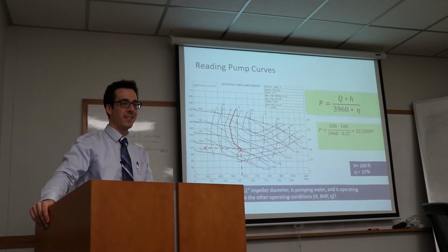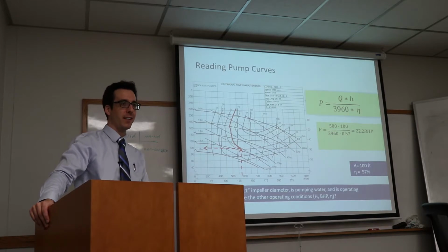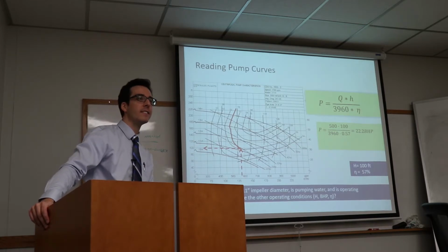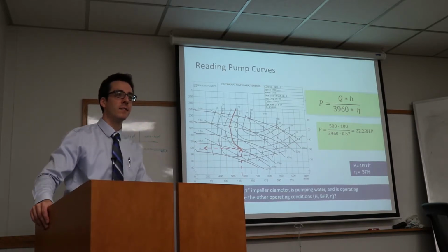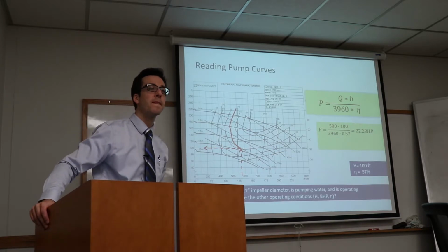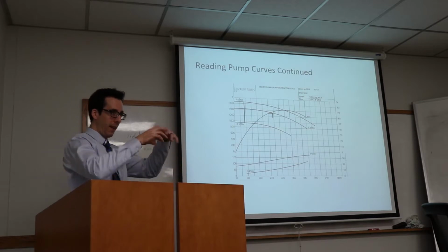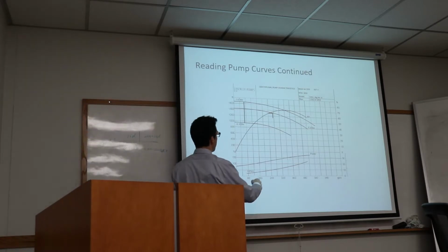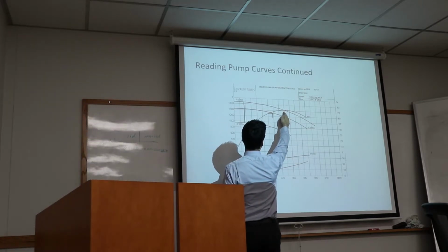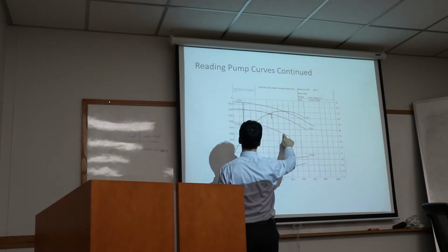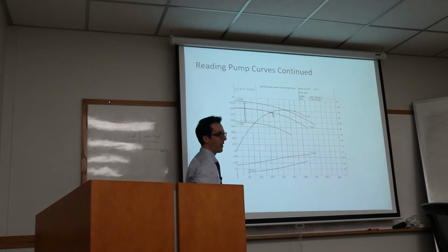Yes, that's right. So this is a fixed speed pump. We'll get to VFDs later on. Yes? But in the other curve, it's not dependent on the impeller size, right? Sorry? In the other curve, the one in the next slide. Yeah, so this one, it's a little bit harder to see without the zones, but yeah, it matters too. Because if we're given the best efficiency here, it is going to be different depending on the impeller size.